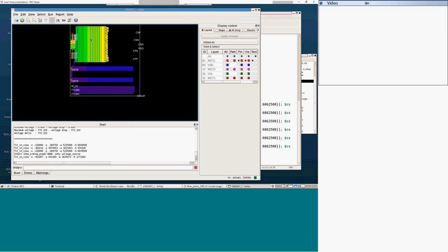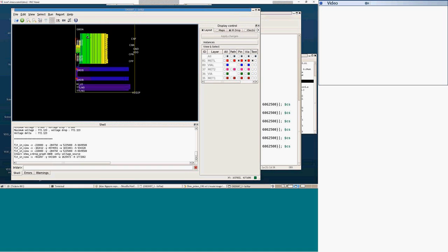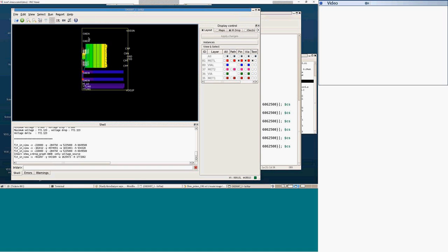And for this area, because I created a uniform distribution of current sources, the tool assumes that a proportional share of current is consumed by this area. It might be a wrong assumption, but when you are a designer, you can assign it better. It says what you see: such a narrow connection to this area is not adequate, assuming this model of current consumption. So it helps you estimate eventual IR drop problems even at the stage when you just create your power plan, without using any SPICE netlist.